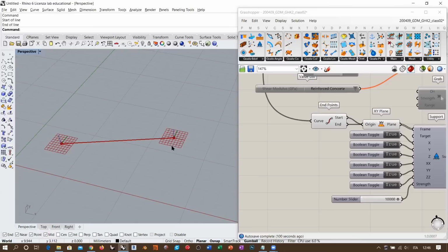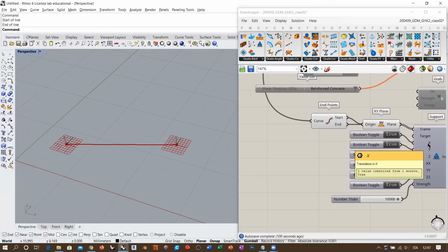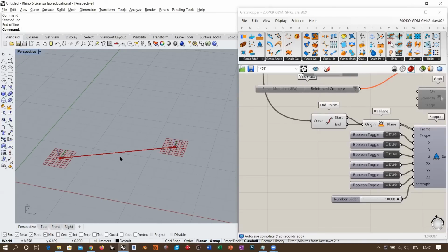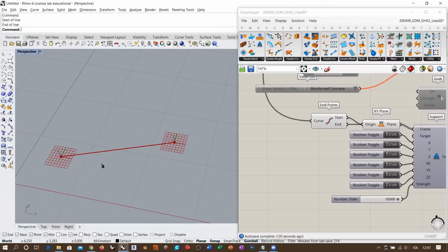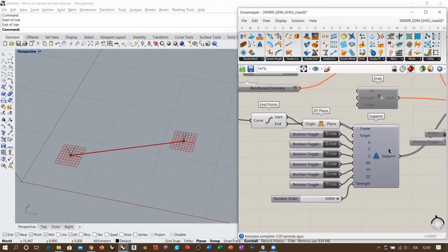And eventually, we want to avoid, for example, to us, X movement should represent the X movement along the line of the beam, the longitudinal axis of the beam, okay? Now, this is not mandatory. If you want to frame this and just avoid any type of movement in any of the 6 degrees of freedom, then there is no particular reason for changing the orientation of the XY plane. In the end, nothing is moving and nothing is rotating.